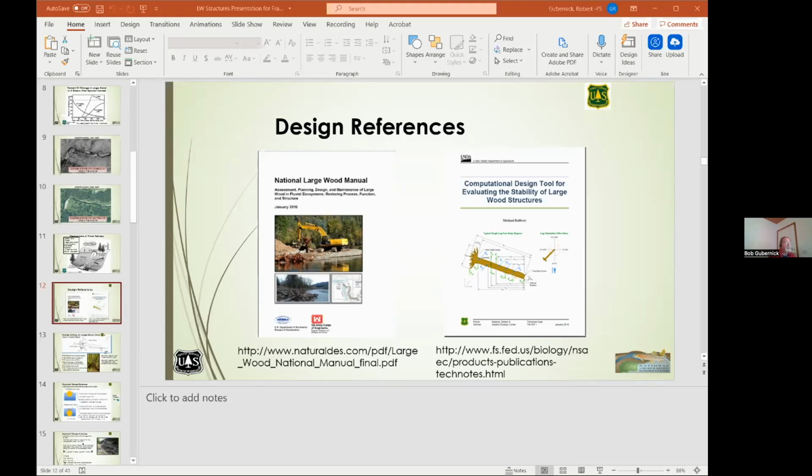I have not done a huge amount of looking for tropical environment woods, but I would strongly emphasize that anybody building these structures try to utilize the most rot resistant tree type as possible. Also, if you are in very warm, humid areas with high decay rates, use as large a tree as you can, because if you use too small a one, it will be gone in a short period of time.